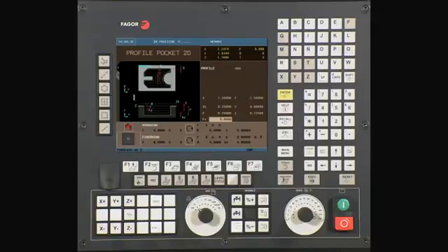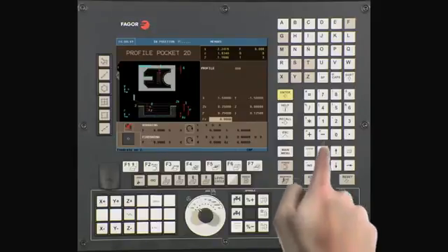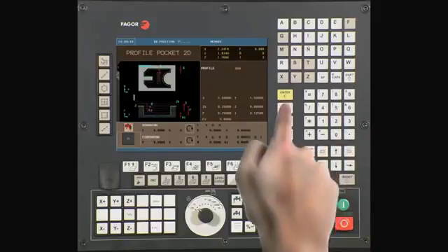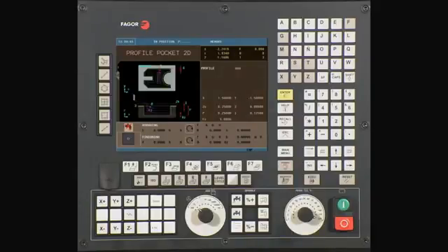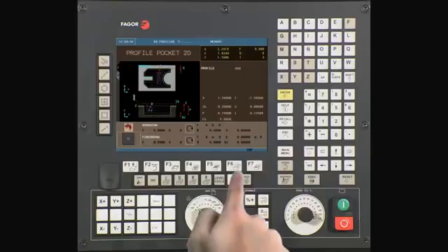FZ. This is the penetrating feed rate. This value is entered in inches per minute. In this example, we'll be using a value of 5. Press Enter to continue. Using the half key to select if you want coolant off or on during the machining process, press Enter to continue.